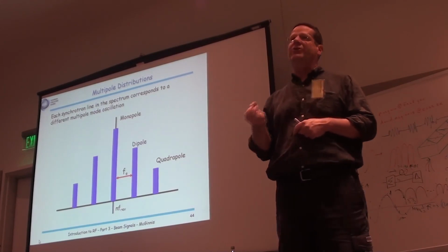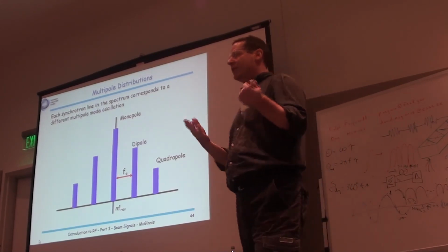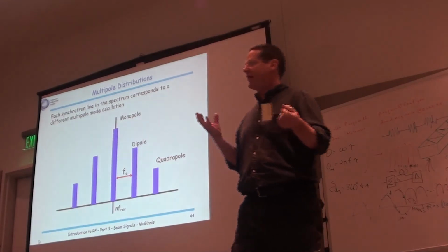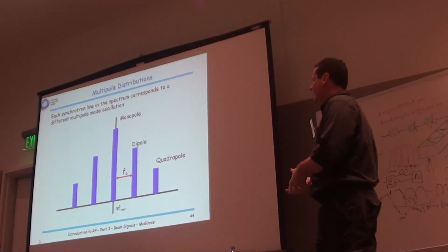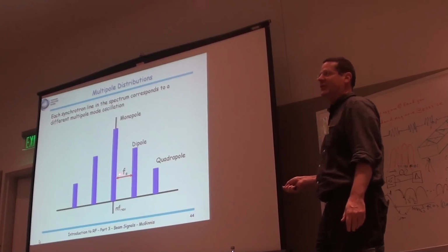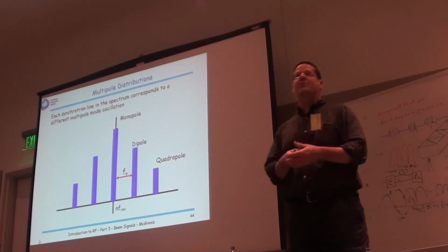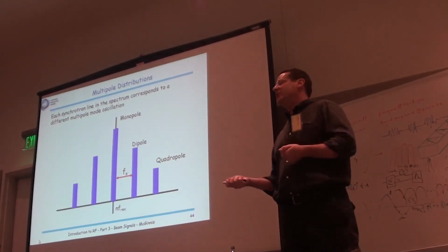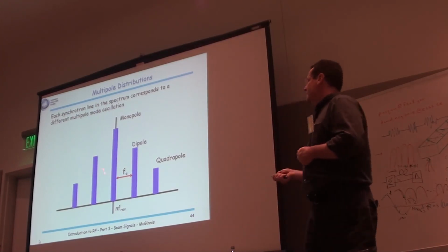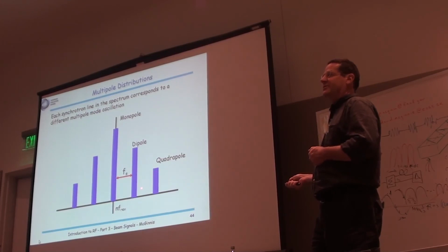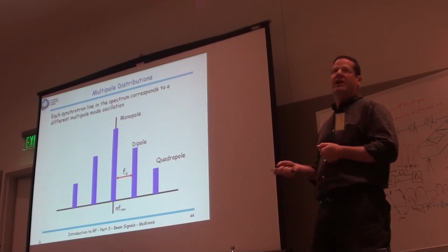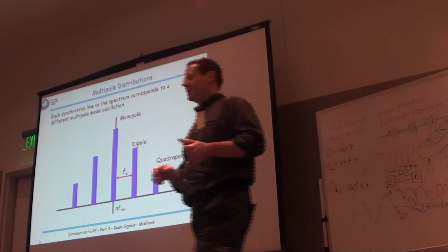So this allows you to build dampers that are specifically tuned to the multi-modes that you have. At Fermilab, I know this because I built these, you'll have dipole dampers that look at the phase, and they look at the first synchrotron line. You got to design your filters right for the first synchrotron lines. The quadrupole dampers are built for the second synchrotron lines. For the dipole ones you use phase detectors to see, and for the quadrupole ones you use bunch length detectors to see. And then you can actually go ahead and damp the lines that get excited.